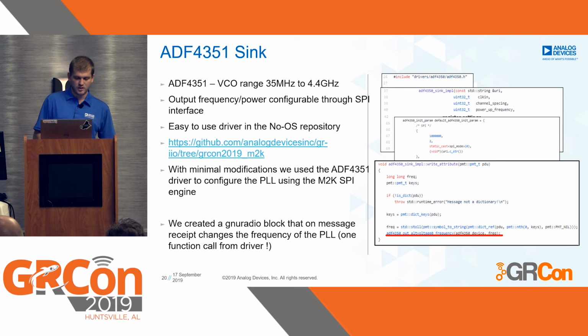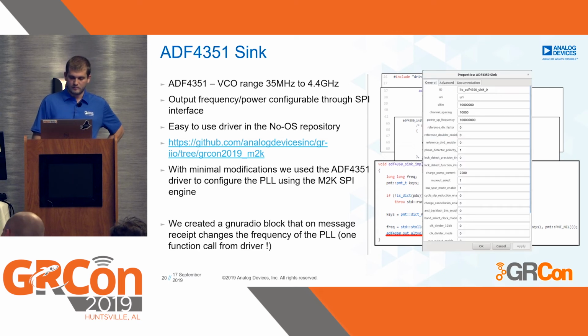We run this function from the driver, the ADF4350 set frequency, and this is basically it. We get the frequency from the message, and the driver handles all of the SPI transactions between the M2K and the PLL. So this is what the block looks like. Here are all of the registers that you need to set up, and you're good to go after this.